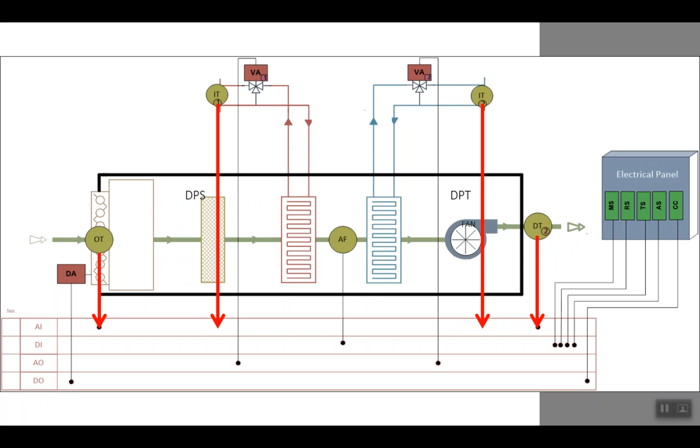The system in closed loop is going to control the fan, for example, gradually between 0 to 100%, and open or close the cold or hot coil to provide the adequate supply air temperature for the rooms. So this is one of the key sensors we need. Also, the temperature sensor is provided with an analog input.